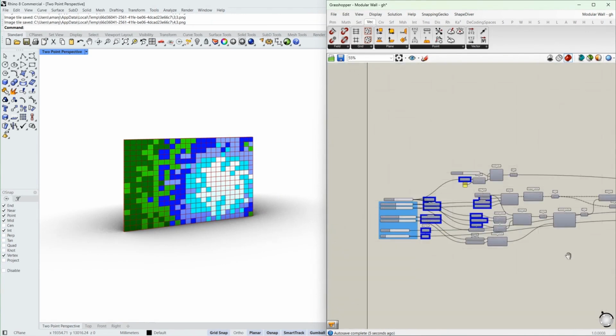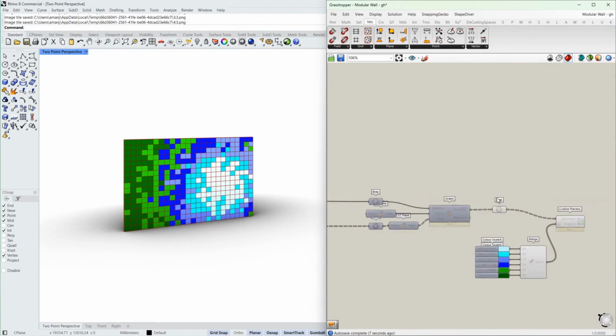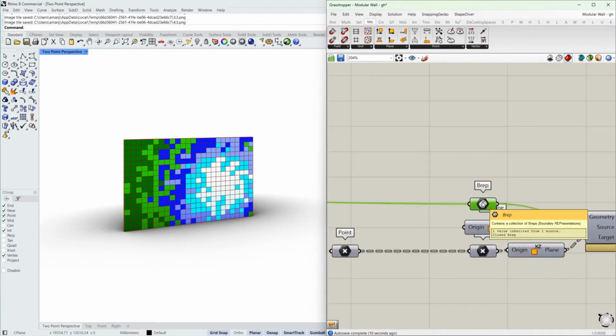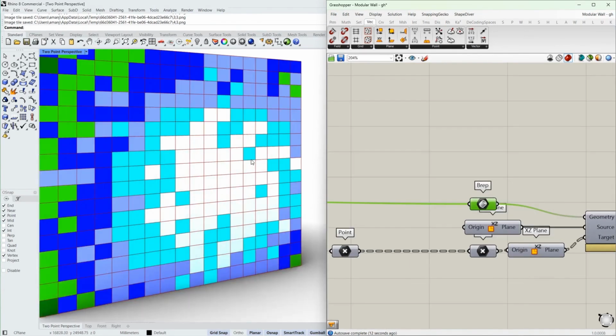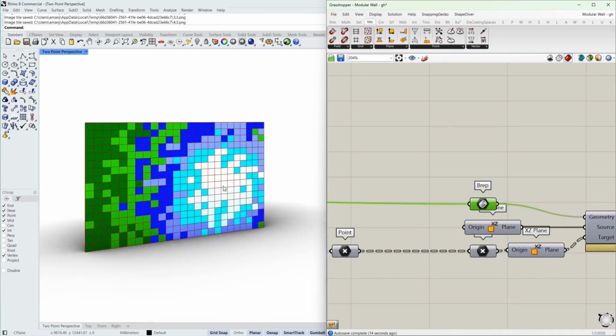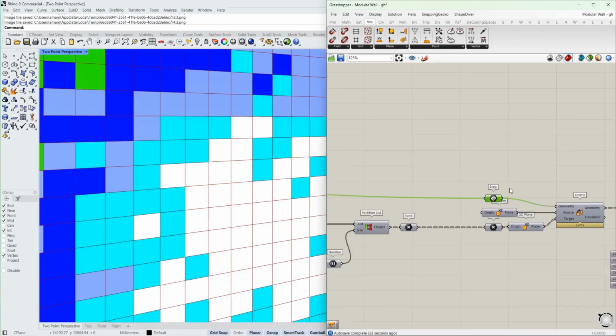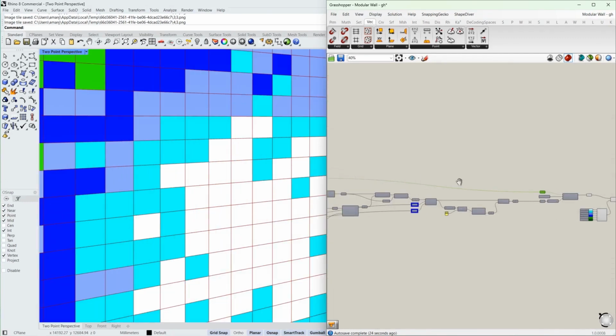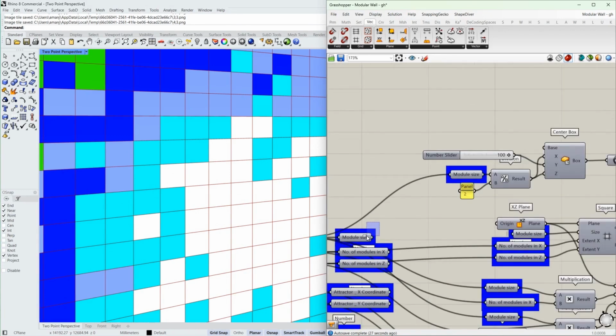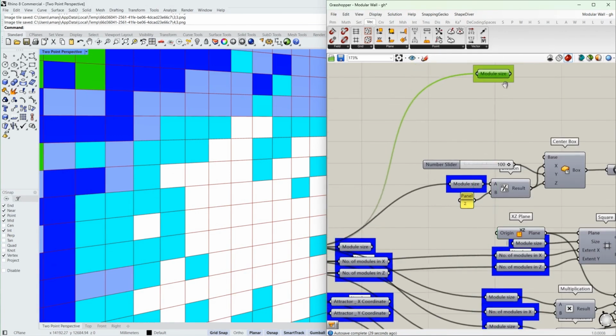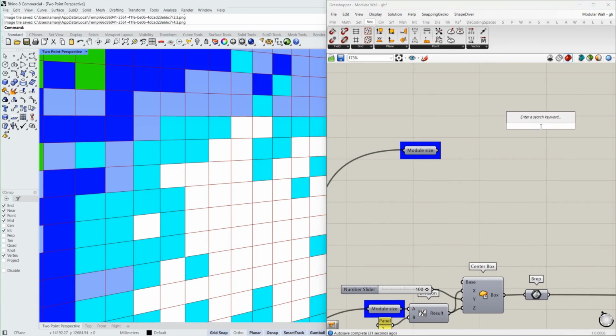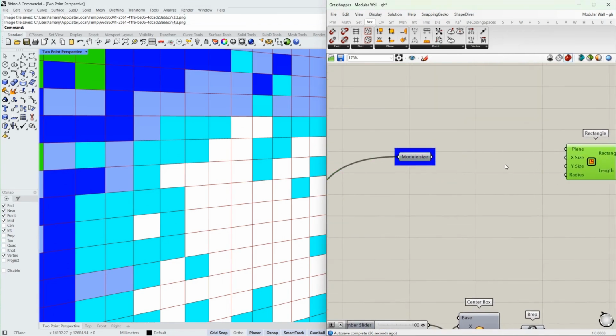As an additional layer, we can replace this module with custom modules. So rather than following a single module across all 6 buckets, we can create different shapes for each one of them, within the limit of 300 by 300, of course. To do that, I'm going to take the module size. I'm going to use a rectangle and also divide this by 2.